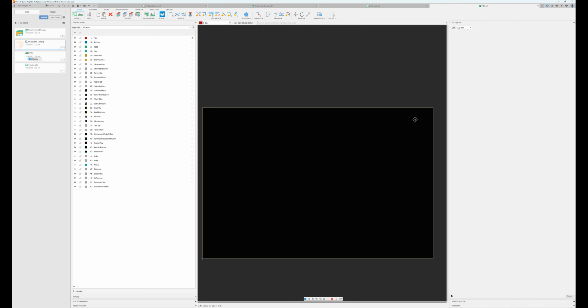And we're just going to change the drill size, because you have a drop down for most sizes, but it doesn't go all the way to 4 millimeters, so you just override it by putting 4 in there, hitting enter. So there's your hole. So you just put it here, let it snap into place about right there, and click, and let it snap into place there, click, and snap into place, click, and snap into place, click.